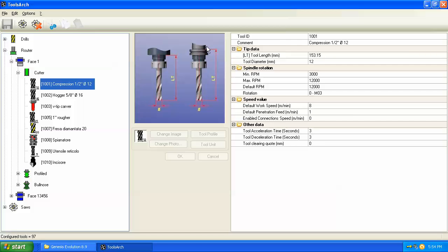Then we'll define the tool length, which is measured in most cases when we've got the tool in a tool holder, an HSK holder. We measure from the shoulder that mates up with the underside of the spindle. This shoulder on the tool, just as it's drawn here, marks the entire tool length. So we measure from there to the tip of the tool. Be sure to factor in this part of the tool. If you measure the tool too short, then you can make the tool go too deep into the material.